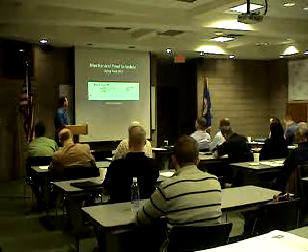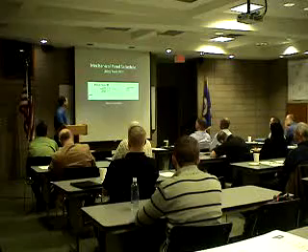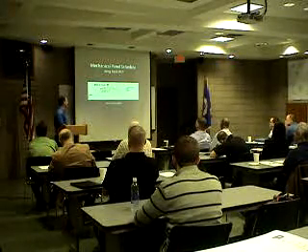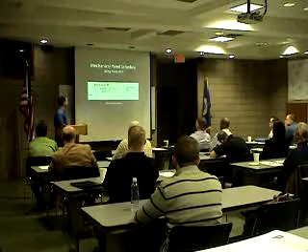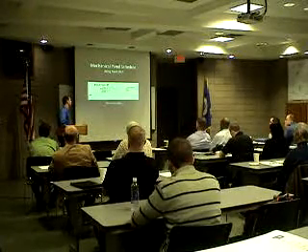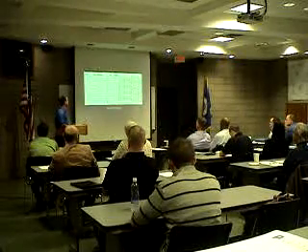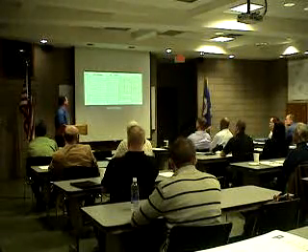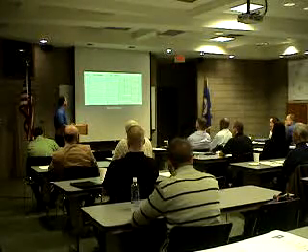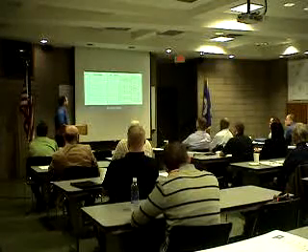Now we'll take a look at the mechanical panel schedule. This was done using Revit as well. So for the main panel, we use a 500 amp panel, and it is a 120/208 3-phase 4-wire panel. And as you can see here, this is basically what the circuiting looks like for us when we came in. Obviously a 3-phase schedule. And you can see the receptacle panel, air handling unit are connected on here. That's showing your demand load for each one.